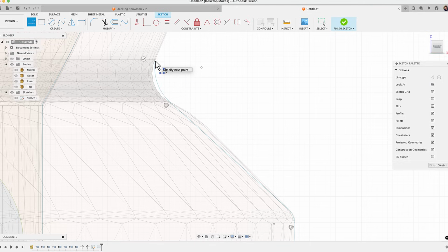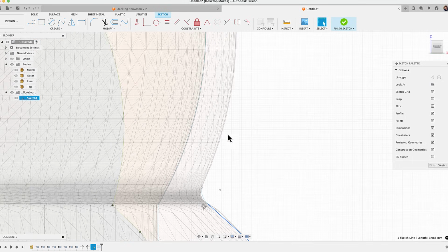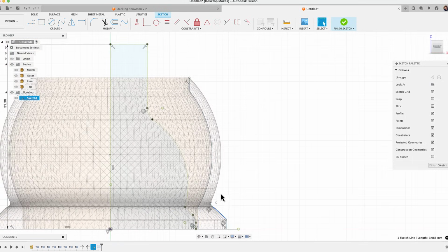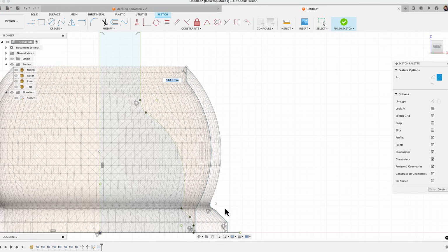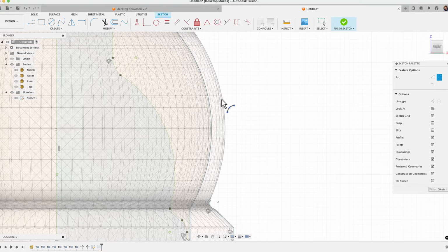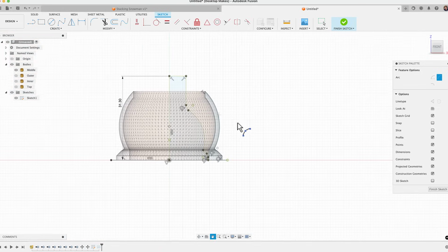Now this is the part where I'm not gonna worry so much about matching this perfectly. I just wanna keep the design simple where I don't need complexity. So we're gonna go a line to an arc. If you did want, you can tweak this and use the spline curves and more arcs to follow that exactly, but we're gonna keep this on the simple side and only fuss about the things that really do matter. So now we're gonna connect those outer 2 points again with our 3-point arcs. So here we're gonna click 1, click 2 here, and then just zoom in to match up that radius, and then we're good.